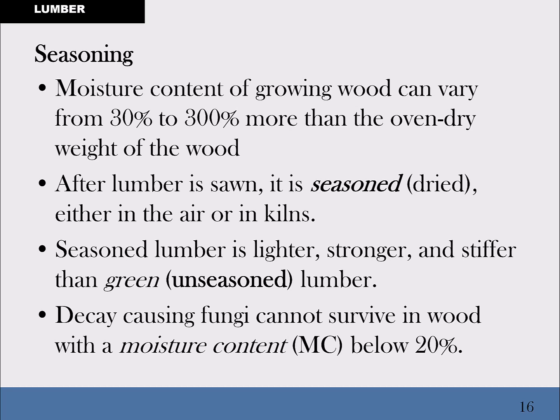As we tore out the drywall and the insulation and all the contents of the house and got that to the curb, everybody was waiting and fighting with blowers and dryers to dry out their house enough to get the moisture content back down to 15%, because that's the magic number that we consider to be dried out enough to close it all up again.